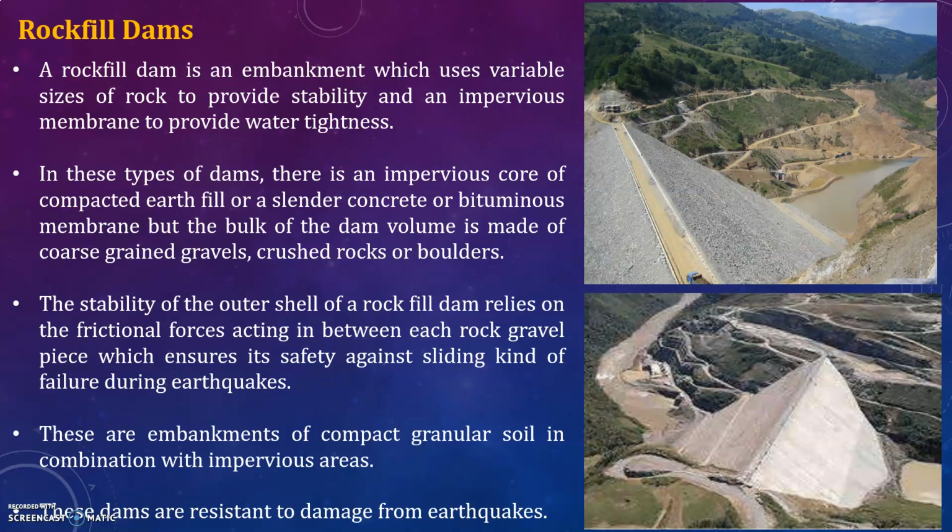Let us see some of the advantages and disadvantages of earth and rockfill dams. Earth dams can be constructed almost on any type of available foundations. However, rockfill dams impose some restrictions on the quality of foundation, but they are much less rigid than those required for any other type.